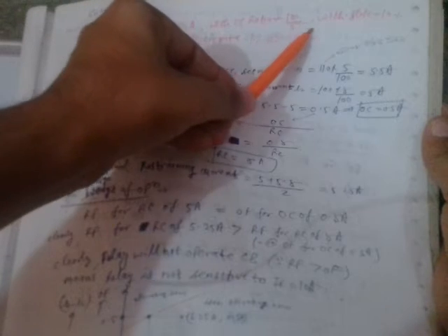Now the question is, for 110 ampere current, the fault current is 10 ampere that we have assumed, going to ground from the fault point. CT ratio is 100 by 5, and if you set the percentage slope to 10%, will this really operate or not? That is the case number 1 that we are analyzing.